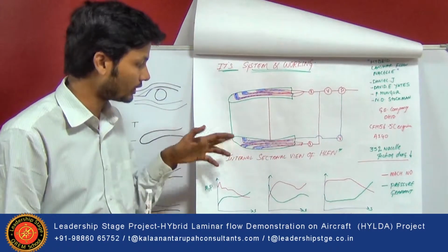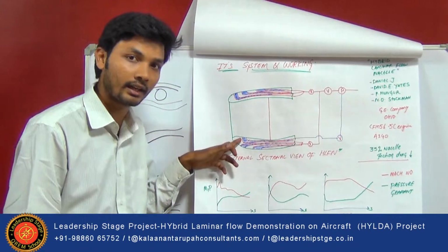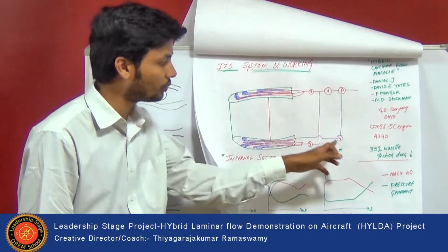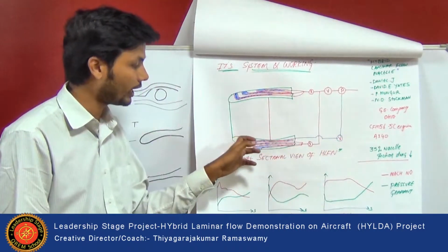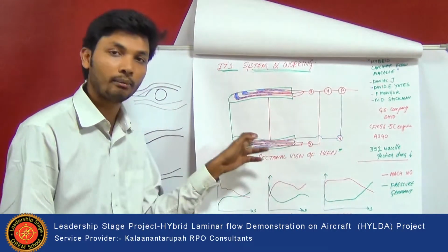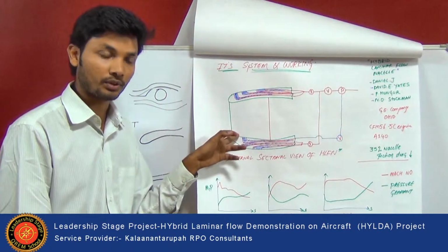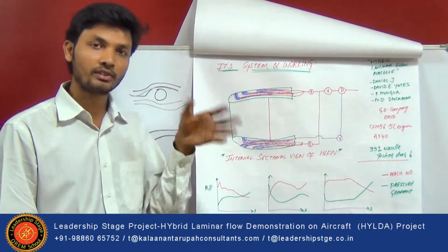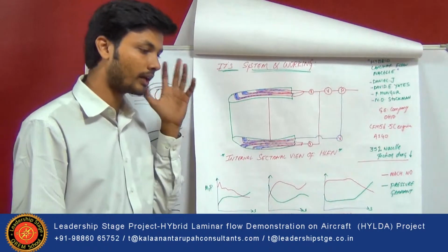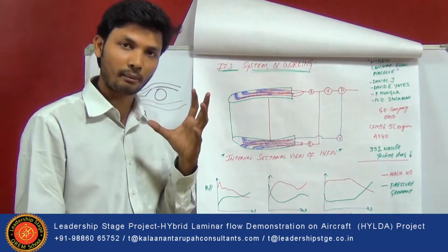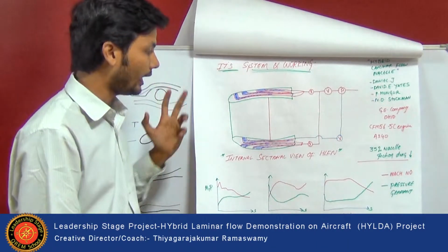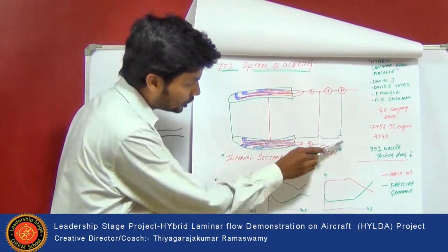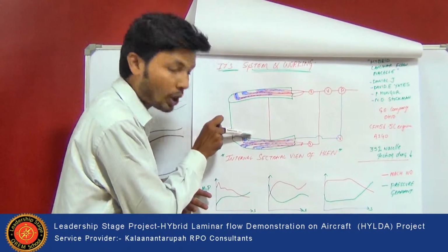So for that reason, what they do is they just open the internal duct over here. So only this wall will be open. So this will suck the air over here, and the suppression flow can be eliminated by this process. Whereas at the top of the climb, at the cruise time, at the highest point where the aeroplane will face the maximum Mach number and the maximum mass flow rate, at that time they will close this wall. It means the suction of the air will stop in the internal.